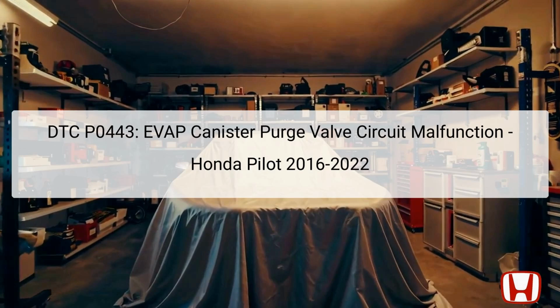The DTC P0443 stands for EVAP Canister Purge Valve Circuit Malfunction, indicating an issue related to the evaporative emission control system in the 2016 to 2022 Honda Pilot. This diagnostic trouble code signifies that the engine control module, ECM, has identified a malfunction in the EVAP Canister Purge Valve circuit. This component is crucial for controlling the vapor release from the EVAP canister into the engine for combustion. This helps reduce harmful emissions and promotes vehicle efficiency.